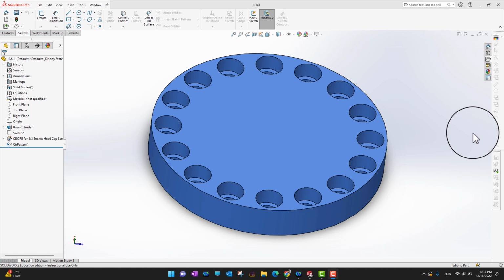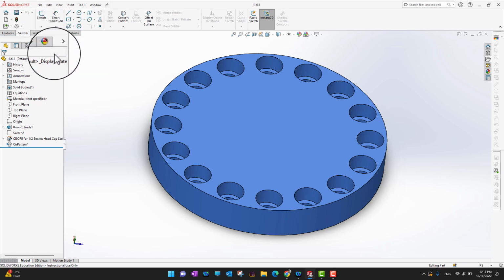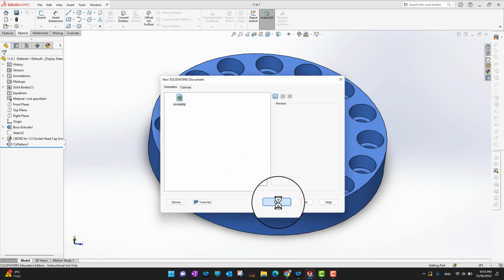Thank you for watching, and in this video we are going to learn how to use circular patterns in assemblies. So the first thing I would like to do is convert this part into an assembly. For that I would go into File and then Make Assembly from Part. Click OK.